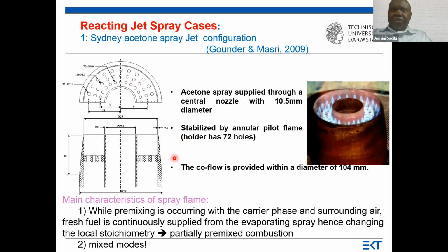So with this, the question is, which kind of spray combustion mode will we have? Normally, in spray, we have either partially premixed combustion or mixed mode. Because while premixing is occurring with the carrier phase and surrounding air, the fresh fuel is continuously supplied from the evaporating spray and changing the local stoichiometry.